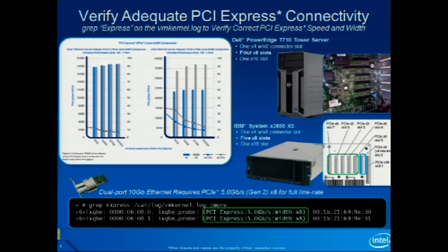I've got this server and I've got these cards in here, and I can't get over 24 gigs. That's the magic number there. If you look at the bidirectional, that's where you'll see that maximum kick in. If you're trying to get line rate on both ports bidirectional, you'll hit about 24 gigs, and then you top out, if it's a by 4 electrically connected slot.